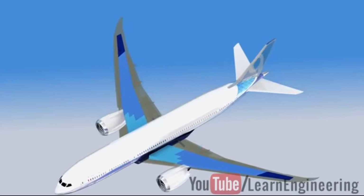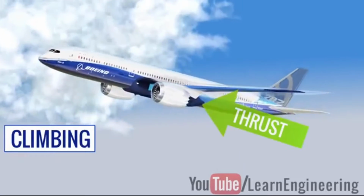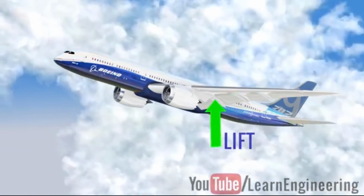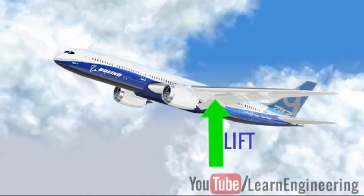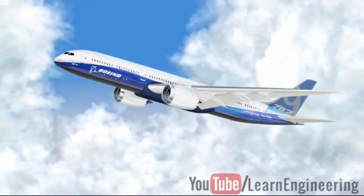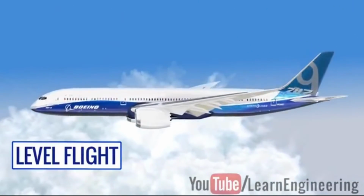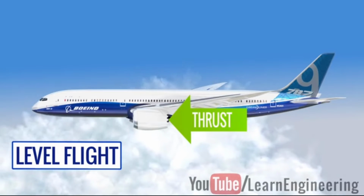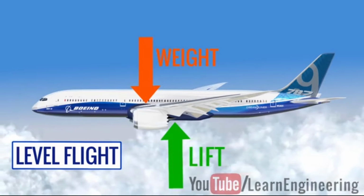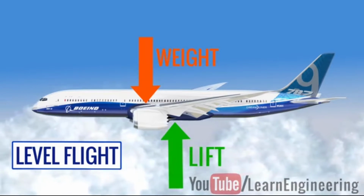After the takeoff, next comes the climb phase of the aircraft. As long as the engine's thrust is more than the drag, the greater the speed, the higher will be the lift force. This will cause the airplane to go up. When the airplane reaches level flight, there won't be any acceleration or change in altitude. You can see that with this condition, the thrust should be exactly equal to the drag, and the lift should be exactly equal to the weight of the airplane.